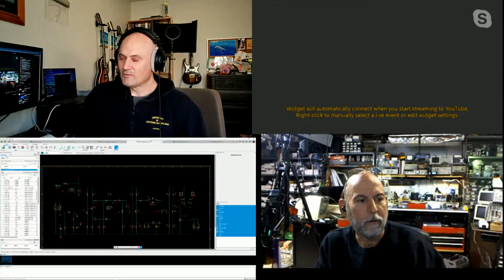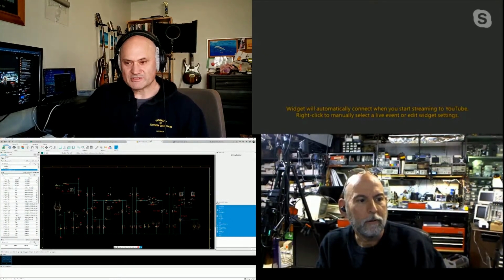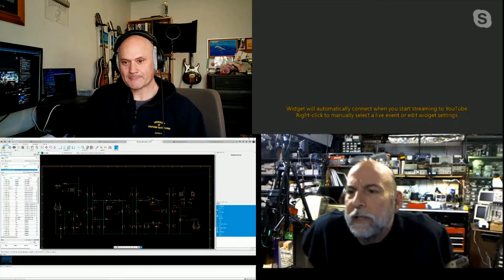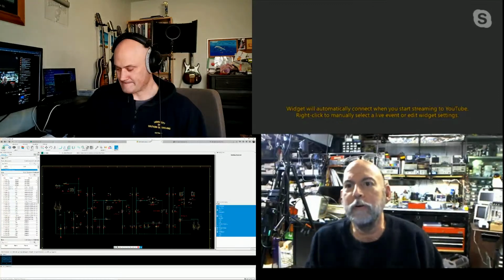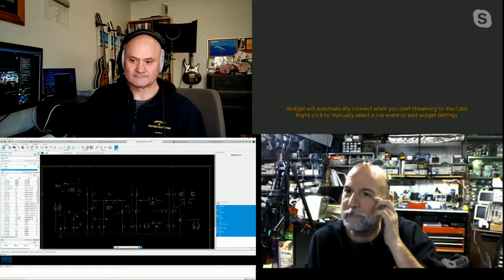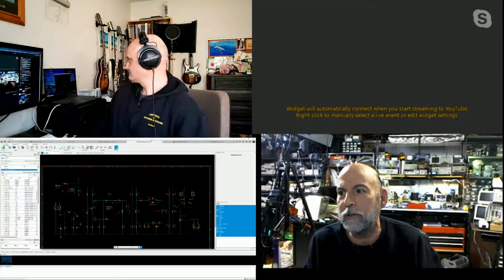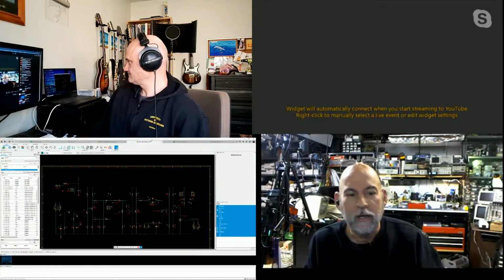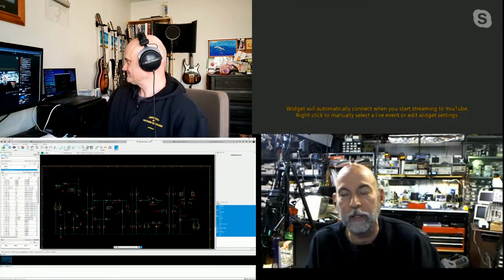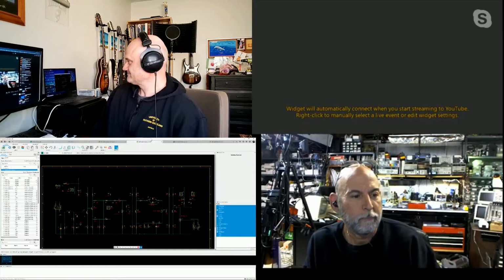Yeah. What do you use when you want to simulate, Bill, normally? Well, I've been using LTSpice lately. My roots, though, is I used HSpice back in the day just because of some of the properties it had for transmission lines and things. HSpice could do a full nodal coax simulation as opposed to lumped.